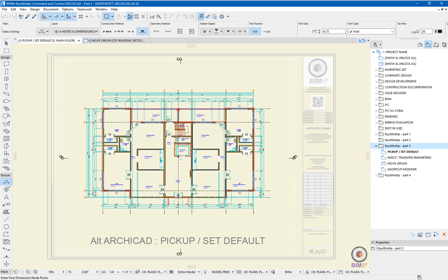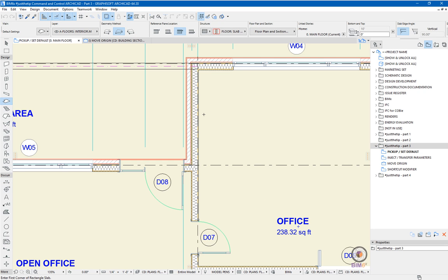So the way it works, let's zoom in. If I move across to a wall here, for example, hold down the Alt key, you can see it highlights, and that's what's going to be selected. So if I now click again, another little flash, but you can see the wall tool is now active, and I have an external wall as the type selected here. If I Alt click on an internal wall, you'll see the defaults change, and I now have an internal. So basically what this means is if I draw a little piece of wall, I have an internal wall.